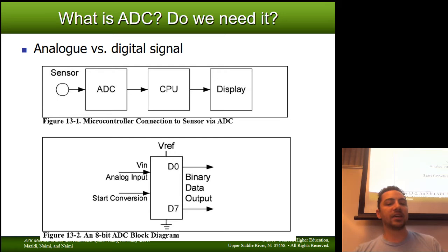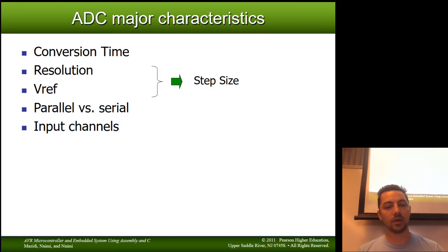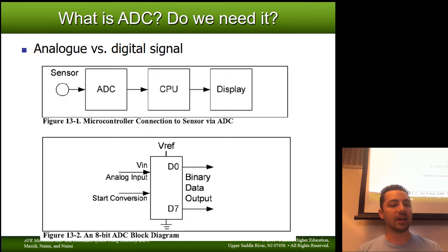So an ADC has some analog input signal. On the bottom it's recorded as Vin. And usually there's some way to say, hey, start doing a conversion. Take whatever the analog signal is at that moment and convert it. So when you see a pulse on this, it says, hey, start the conversion. Then time will pass. That's my clock. Time will pass, and then we'll get